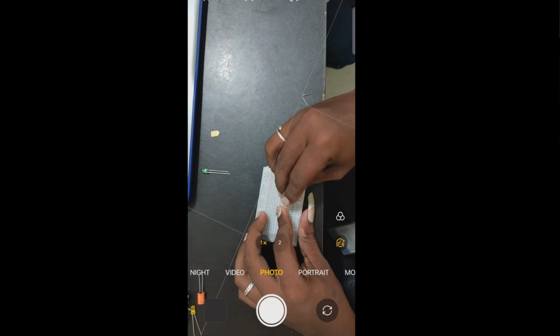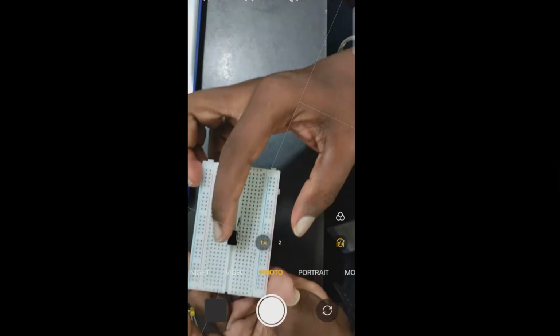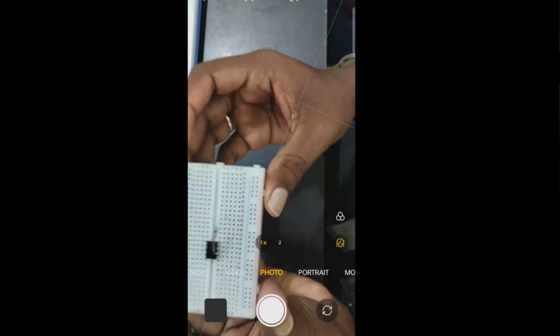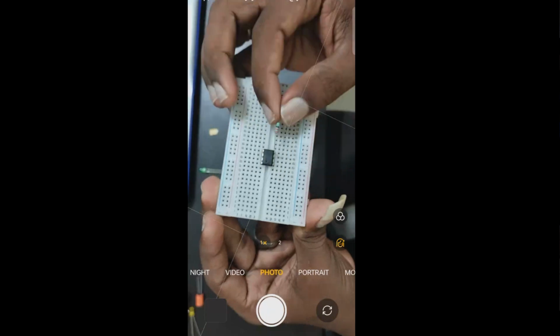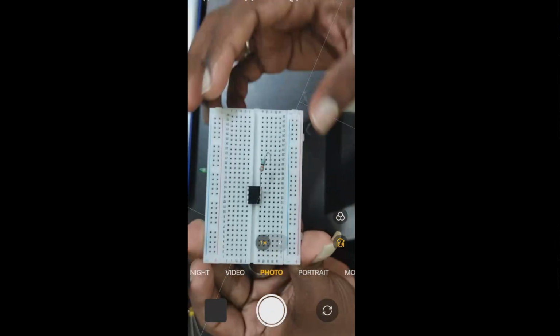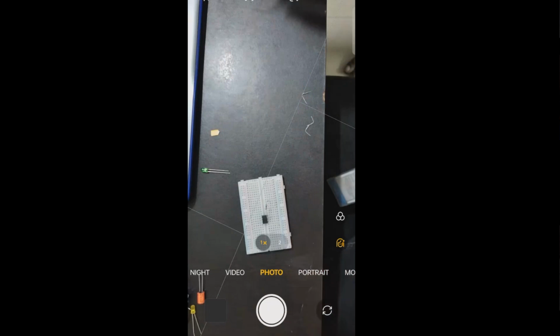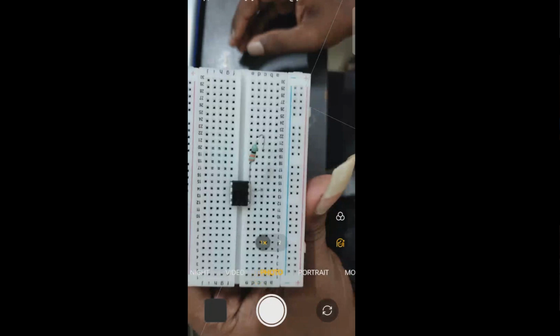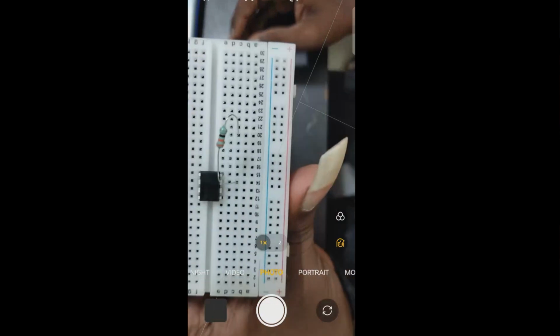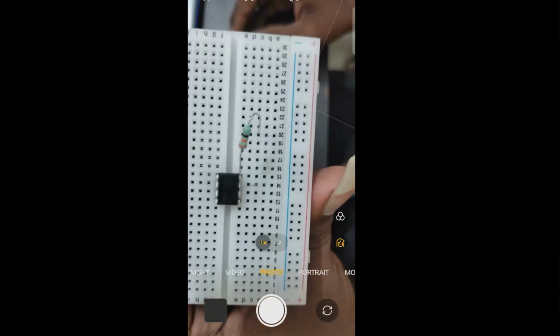So you need to connect one resistor to pin number 3. Do the connection like this. For pin number 3, you count pin 1, 2, 3, and to the third pin you connect this resistor and put it on the breadboard, as shown. So 330 ohms. You have to take a 330 ohm resistor. The color is orange and black. Orange and, sorry, not black, brown.